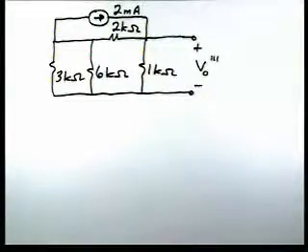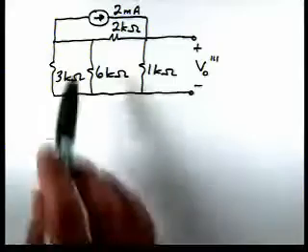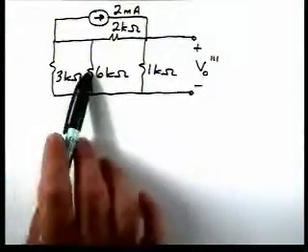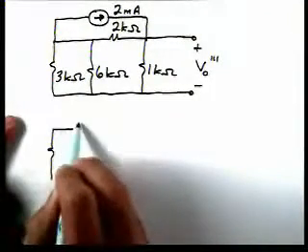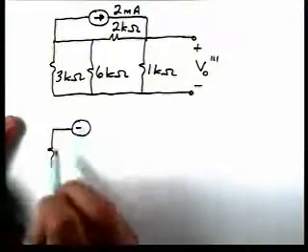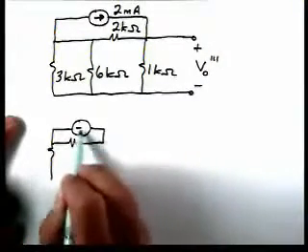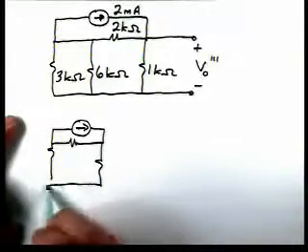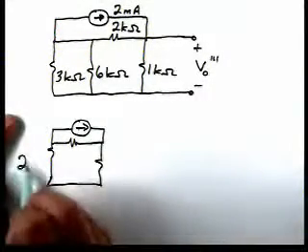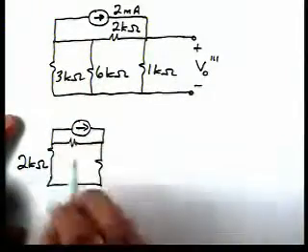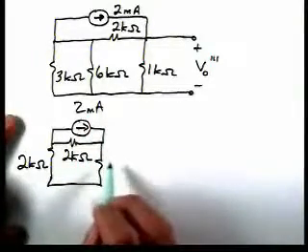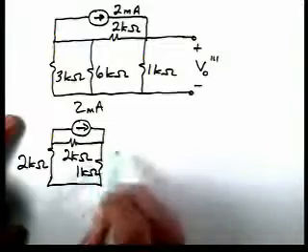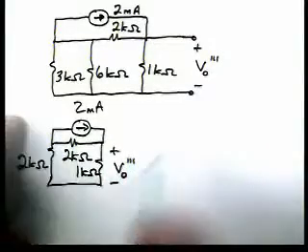There's the circuit. Again, we need to analyze this circuit. If we look now, for instance, these two resistors are in parallel. If we combine those, here's what our circuit becomes. So these two combine here. We have 2 kiloohms here, 2 milliamps here, 1 kiloohm here. Here's the voltage V0 triple prime.